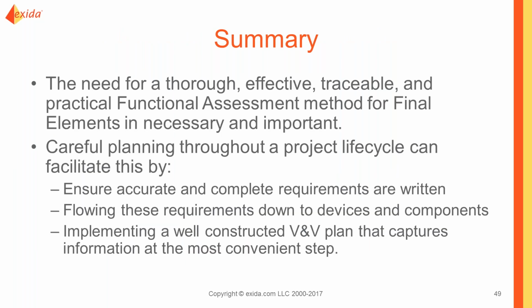In summary, the need for a thorough, effective, traceable, and practical functional safety assessment method is necessary. With careful planning and doing it throughout a project life cycle, that can be facilitated if we ensure we have accurate and complete requirements when we write them, and we keep them up to date if things change.